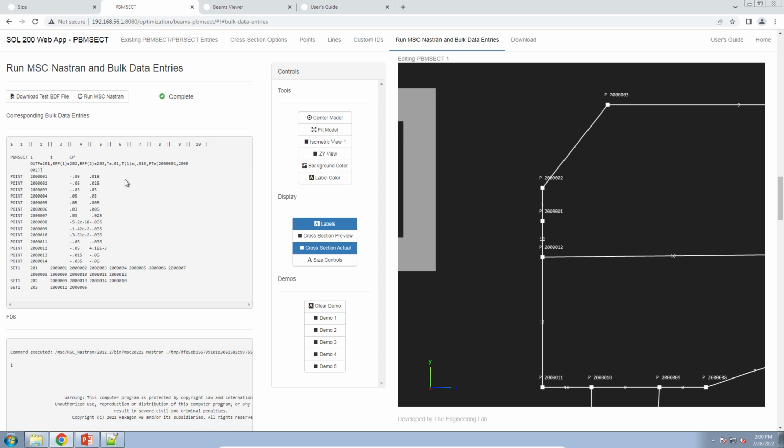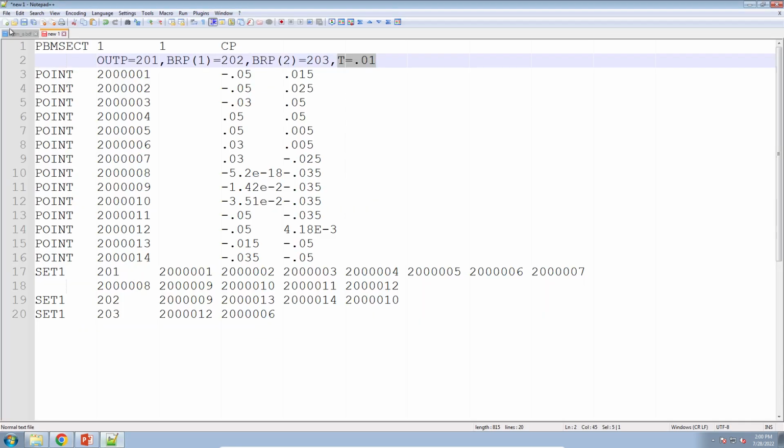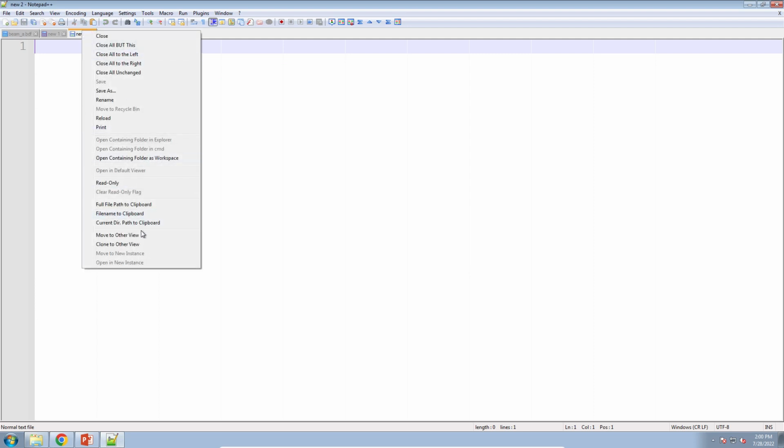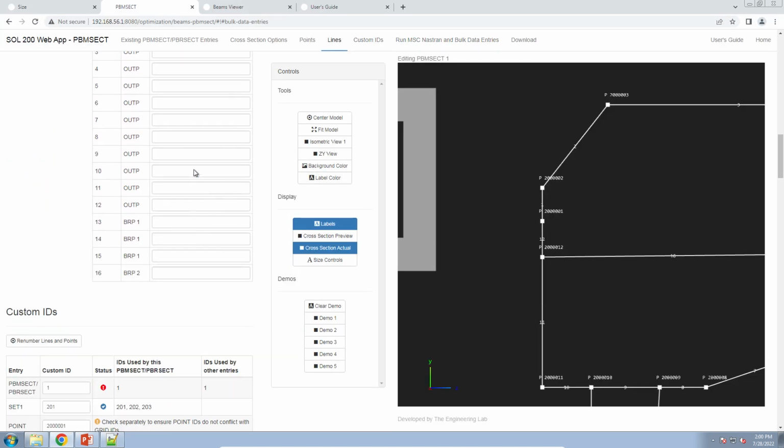The reason the extra 0 is done, let me go ahead and create a new file here and show you that to the right. I get a second thickness keyword that's equal to that distinct value, 0.01, with the extra 0 at the end. Now, if I wanted to perform an optimization, I have the opportunity to vary or optimize this in a different thickness value. So let me go ahead and repeat the process.